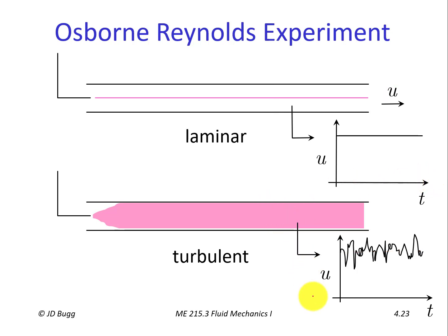However, if we were to do that for the turbulent flow, measure the component of velocity perpendicular to the axis of the pipe, it would also be fluctuating much like this, only it would be fluctuating down here around 0. It might look something like that.